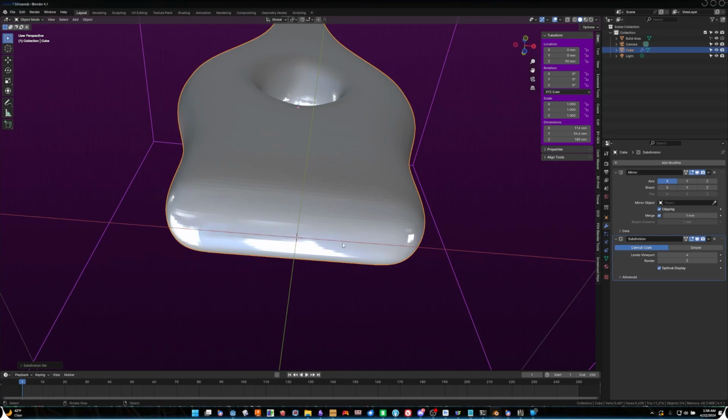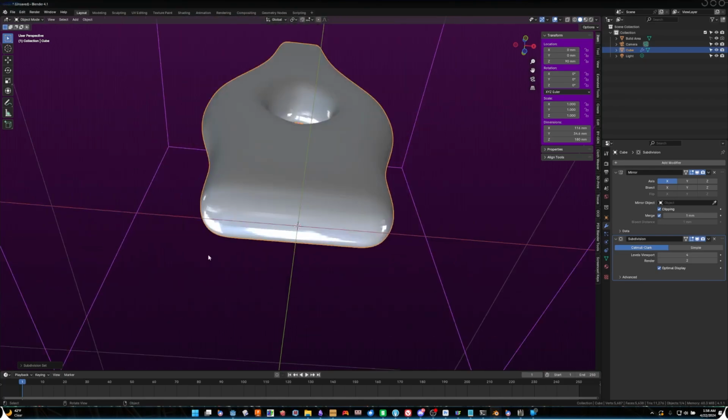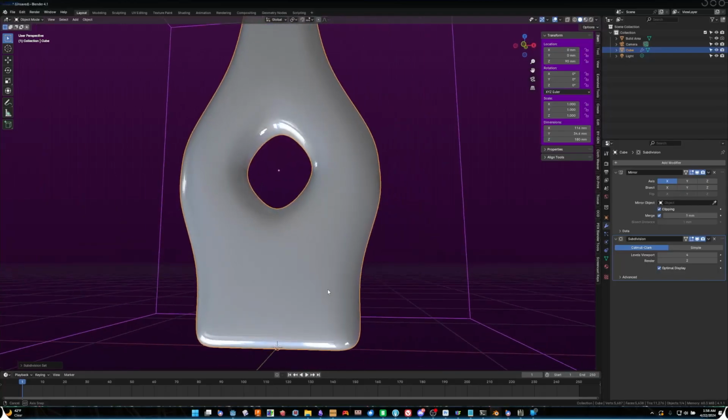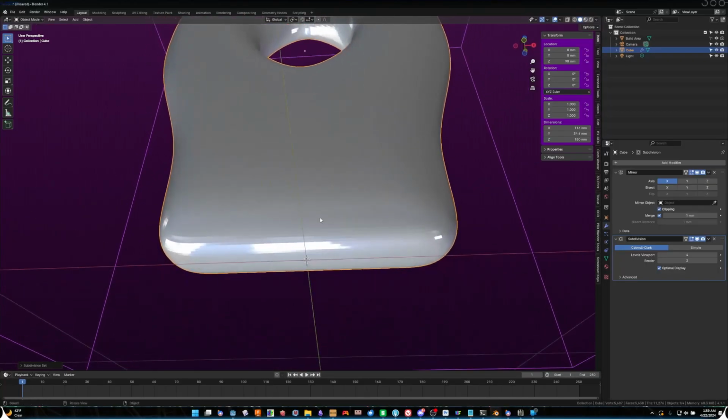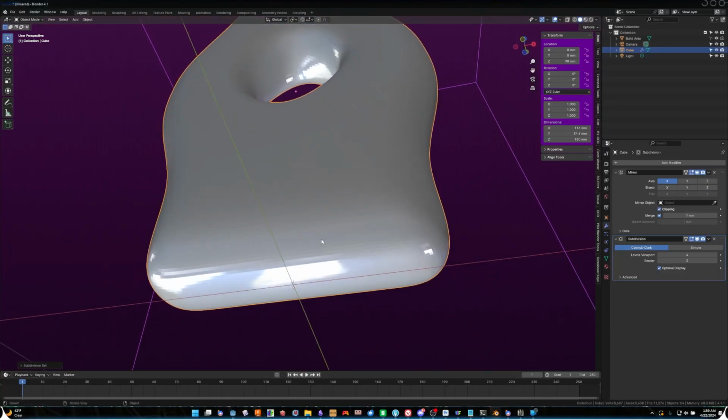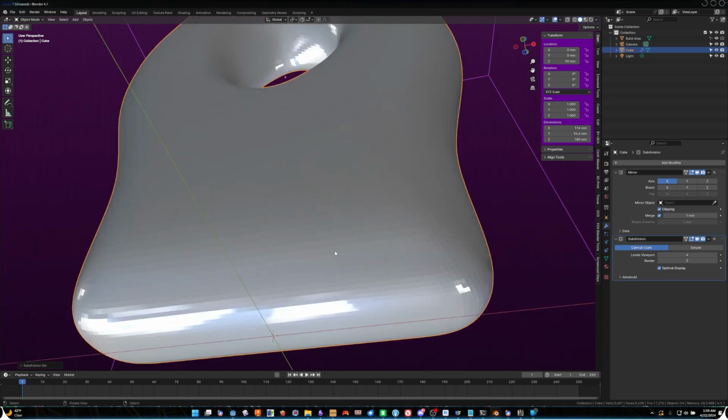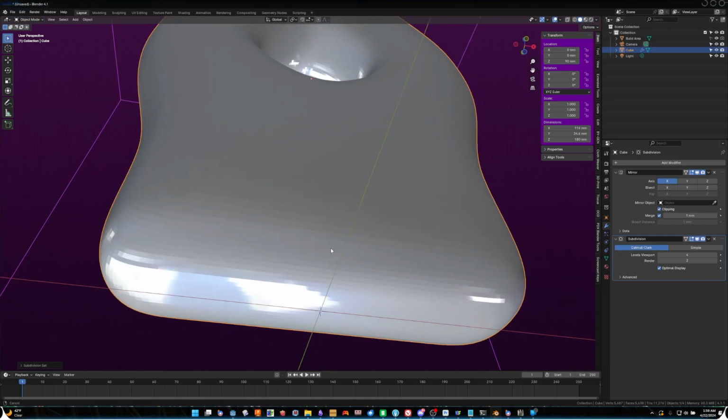This will not 3D print well. It'll be kind of rough on the bottom. And if you've ever 3D printed things with round bottoms, you know what I'm talking about. Typically, well, some printers handle it better than others. Moisture in your filament can have something to do with it. Your settings can have something to do with it, print speeds, etc.